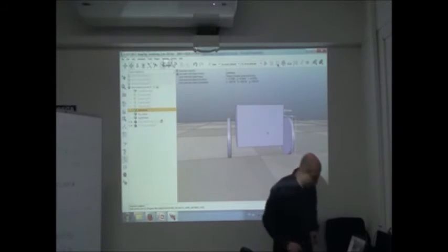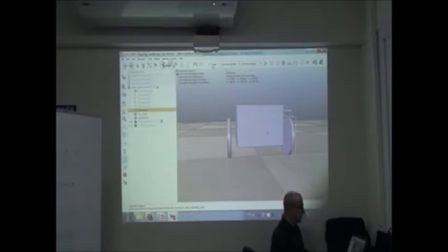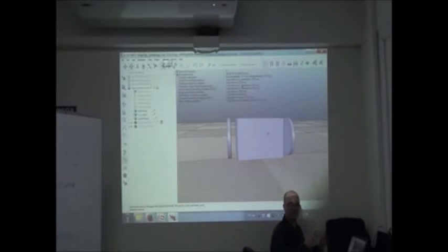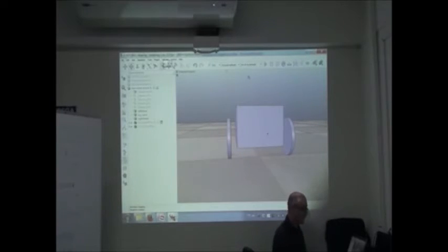Where do I find this dynamic engine? Here, you see, this is the dynamic engine called Bullet. You have ODE, Vortex, and Newton. I don't like Bullet. Let's select ODE. Perfect. Now we press play and it does the same thing, but the wheels are not moving around. They stay in place, which is much more realistic from my point of view.